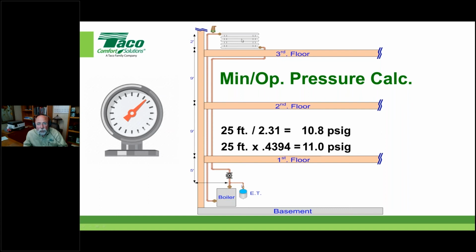So let's see, why do we want to add that 4 or 5 pounds? Well, I put a little air vent up here at the top. And if I want this to be something above 0, then I need to add. And I want it to be higher pressure so I can push the air out. This is showing you a high capacity air vent like our 4900 series, a very high end, very nice air separator for those who don't know. In this case, it's just the air vent portion of a 4900 air scrubber.